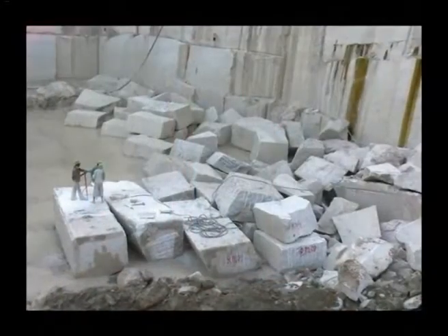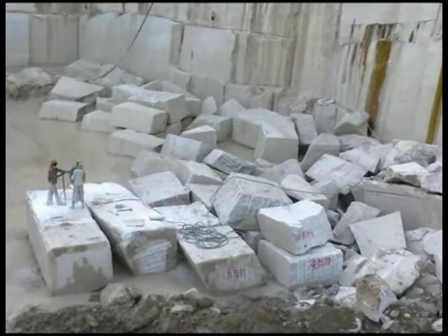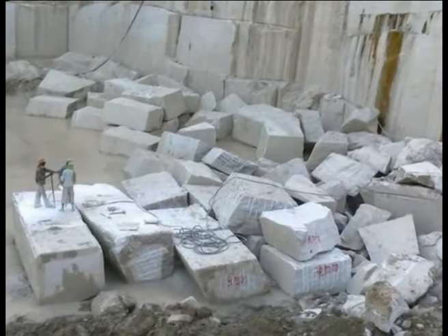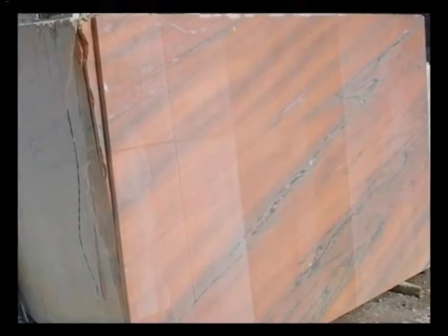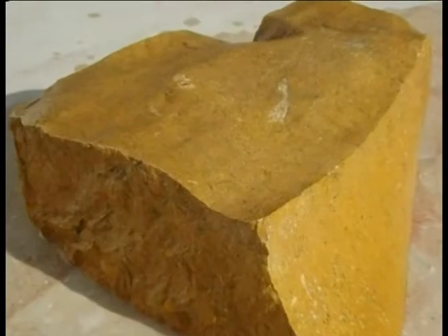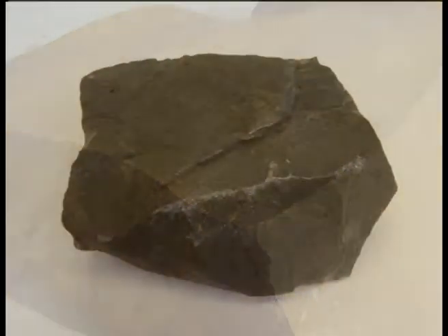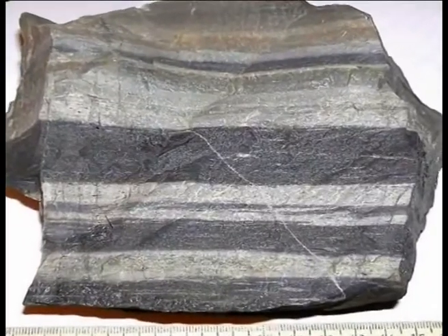The most important source of commercial marbles is the crystalline formations of Rajasthan. One is Makrana in Jodhpur, where we find white and pink marbles. The second locality is Kharwa in Ajmer, where we have green and yellow marbles. The third location is Kishangarh and Jaipur, famous for black and dense marbles.